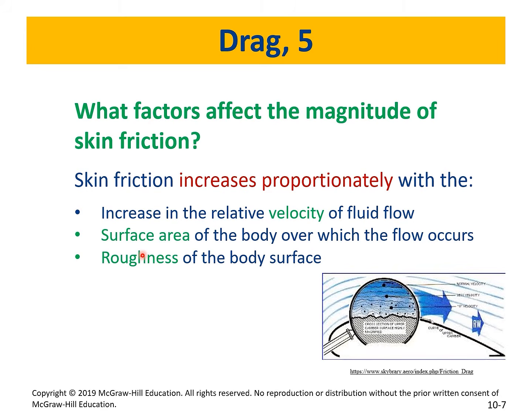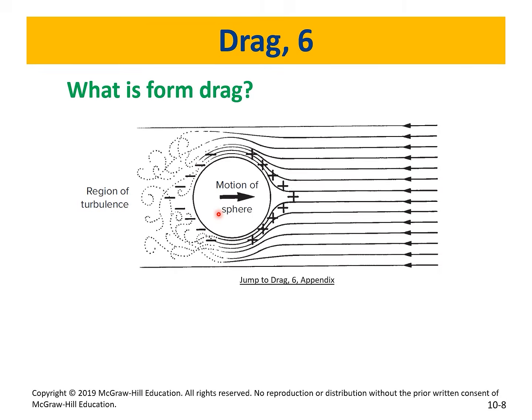And we can use this if, let's say, someone is swimming in the ocean with a very fast current. If you are wearing a triathlon swimsuit, the long sleeves covering all the body, if it's smooth, yes, that is actually reducing the drag force and makes you move faster. So roughness is important, and then the viscosity of the fluid. The larger the viscosity, the larger the drag. Make sense? Now, this is what we call form drag.